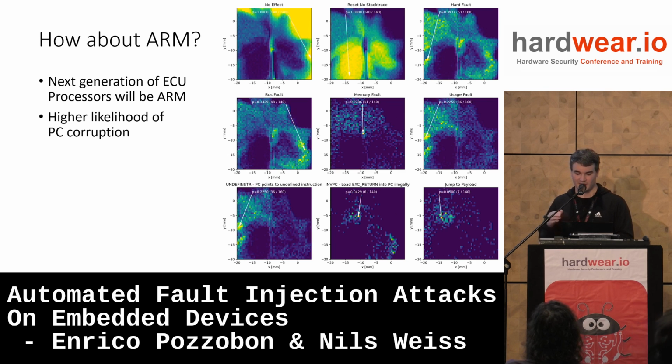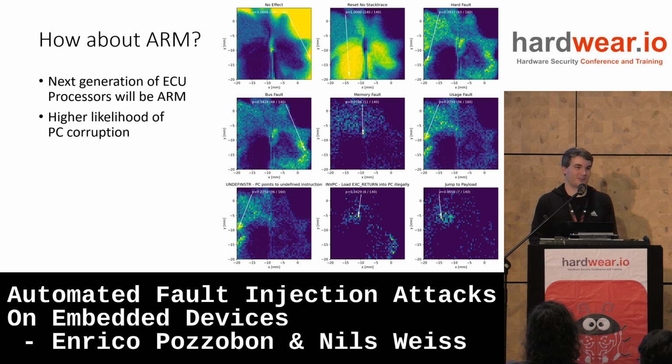It was around 100 times more likely to get code execution, and it was extremely fast to get it. You didn't even need to aim that well. Just spraying random electromagnetic faults was already almost enough. You could have done it with a random attack on this processor. So this was sad to see. Maybe when it's actually soldered on a real automotive ECU, it's going to be better.